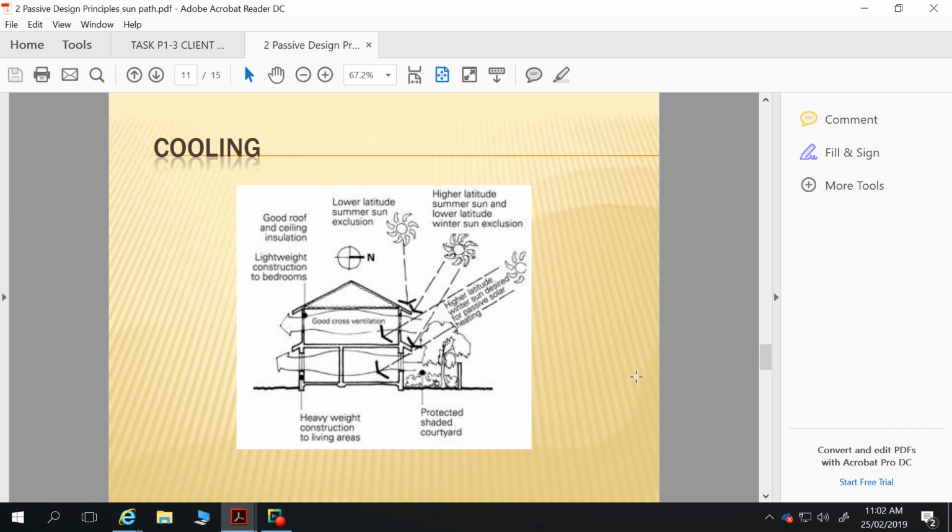Are plants also taken into consideration when we are doing the energy rating? Yes. What you have to do with the person carrying out the energy rating assessment is provide them with information about the trees which are there. You say what species of tree it is, whether it's evergreen or deciduous, what height it is, and what distance it is from the building, so they can work out it's providing shading at this point in time.